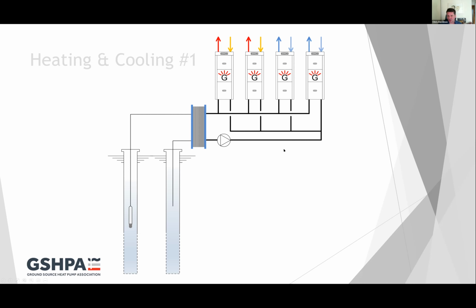And that brings me on to the control of these systems. I've seen an awful lot of people get themselves in a terrible pickle as to how you control a system like this. And the old adage, keep it simple, is the best message I can give you. In practical terms, what we actually do is we look at the temperature of this closed loop here, and we turn the well pump on to moderate that temperature. So all of the requirements that John talked about last week in terms of the licensing, in terms of temperatures, in terms of instantaneous flow rates, annual flow rates, and so on, are all design parameters now rather than controlled.